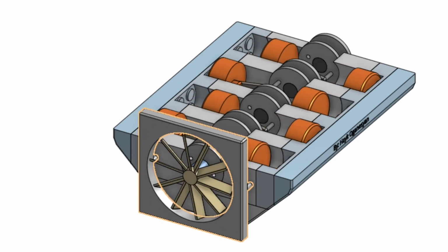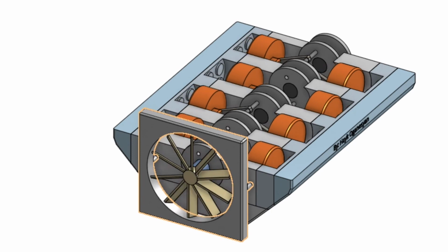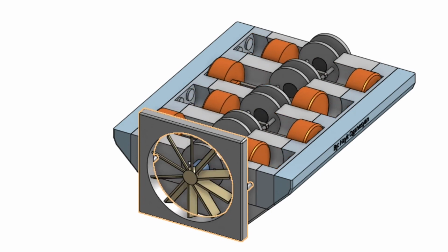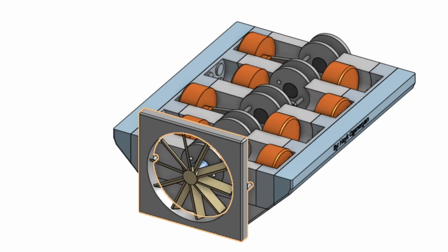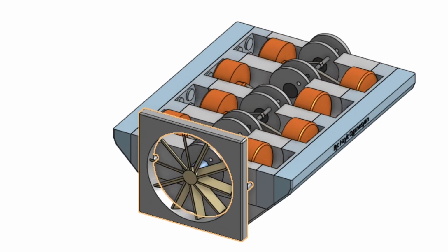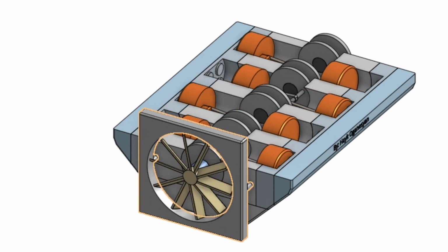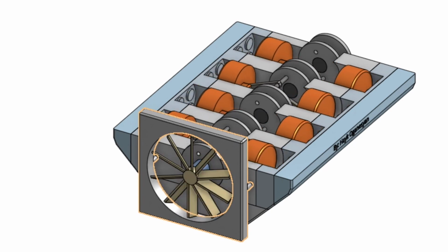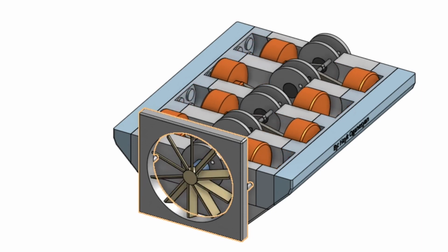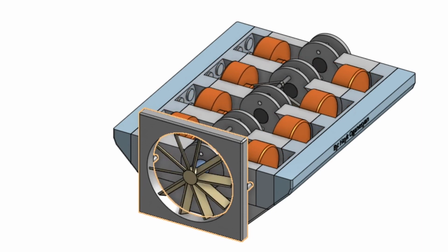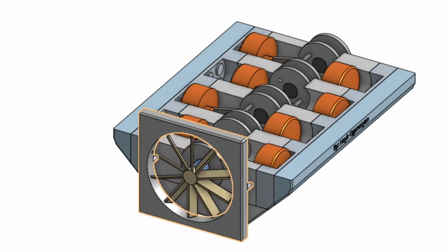It's much harder to work on than a V configuration engine, if not the hardest engine to work on. Doing valve jobs or trying to get access to the engine from the sides is almost a nightmare, and in some cases the engine has to be dropped out of the car. And therefore, it's going to be very expensive to maintain, and if you don't know what you're doing, it could turn into a nightmare. But it's a very nice engine, it has a very low center of gravity, and you still have the power of a V configuration engine, but with a low center of gravity, so your handling isn't getting spoiled either.